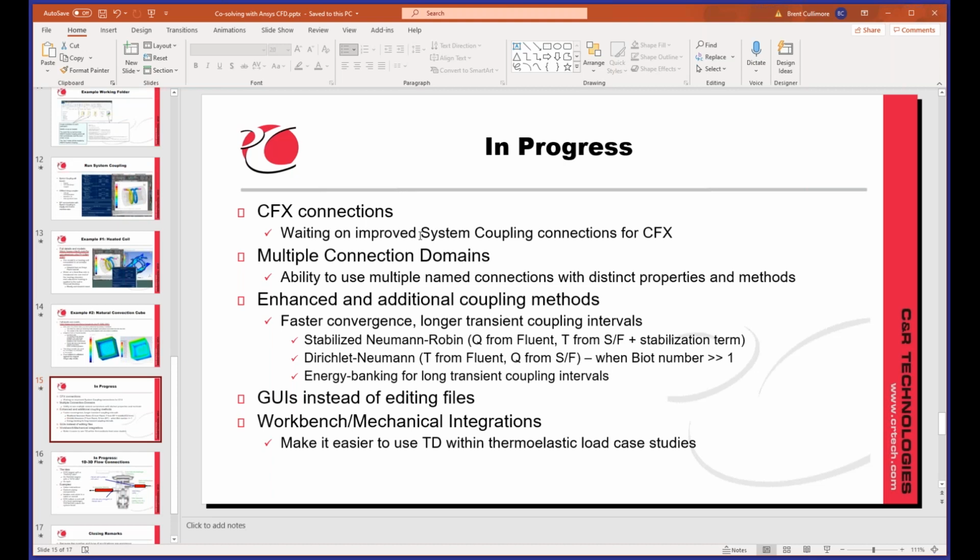But I also kind of wonder, to answer your question, if using CFX to model the pump, it's kind of tough to combine an analysis like that into a what-if you're going 3,000 RPM for 5 hours sort of analysis. So in other words, some of that doesn't translate into, can I treat the pump as quasi steady for a system level analysis? And you may have to go into producing performance maps to do that coupling. So how's that for an answer? You get 3 parts, 2 are soon, and the third is that's a tough one.